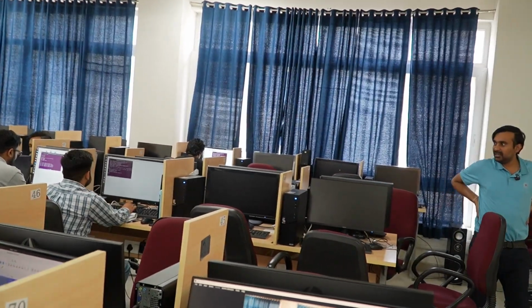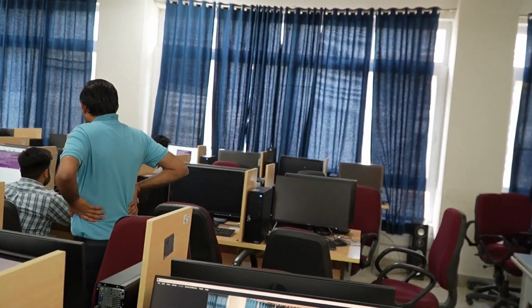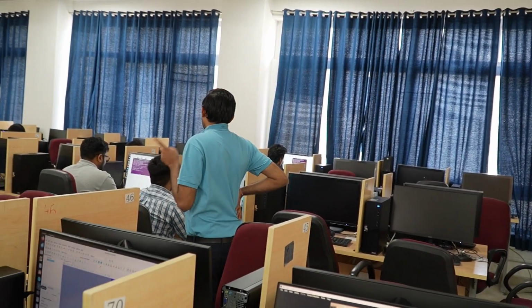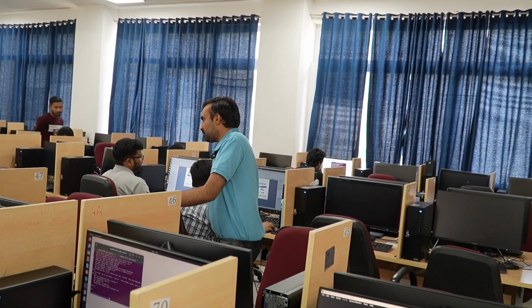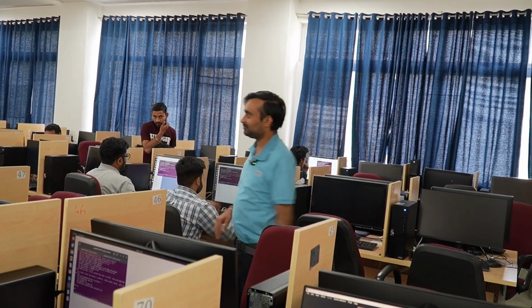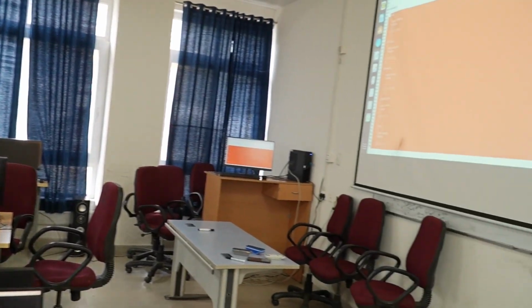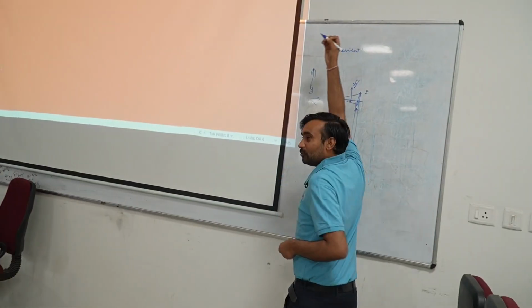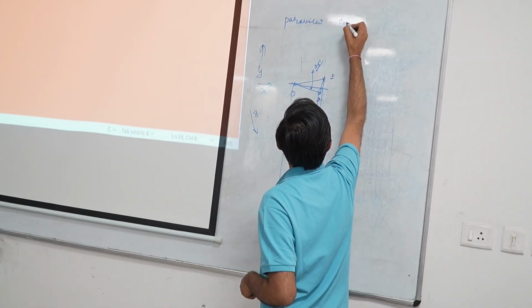Now you need to type the command paraview, P-A-R-A-V-I-E-W, and then put a space. Please type the complete command, otherwise you will not be able to visualize. After paraview, do not press enter. You have to write paraview, space, then hyphen and then touch, T-O-U-C-H.